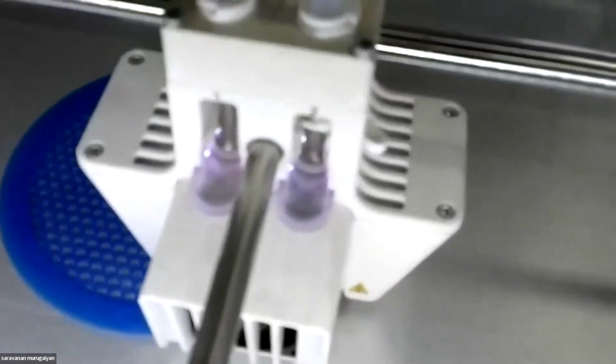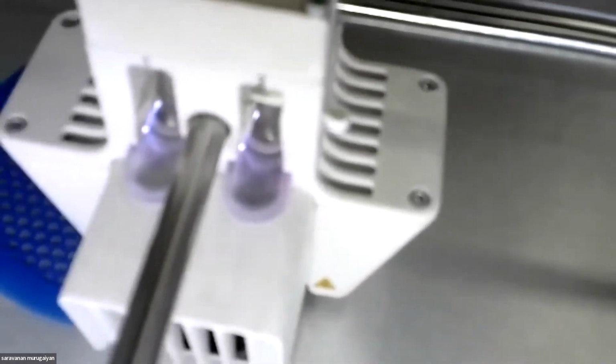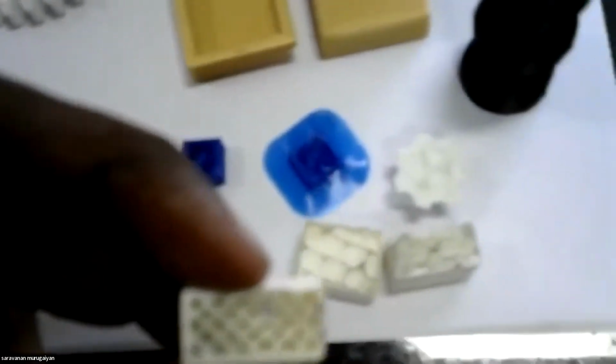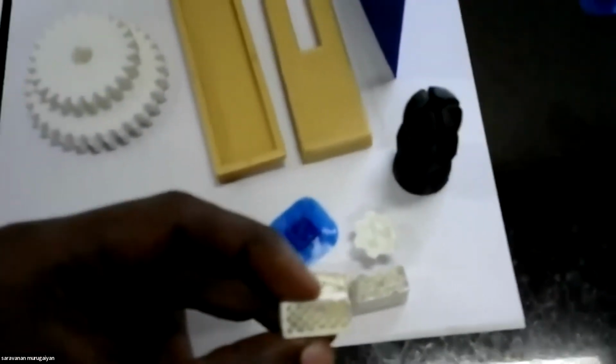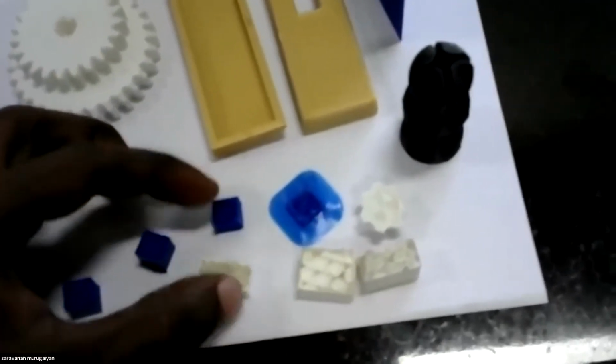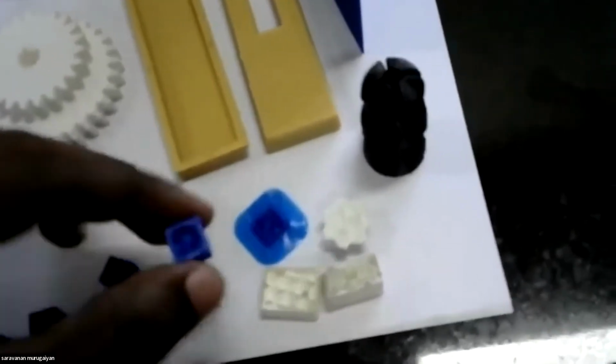As you can see, now we are printing a honeycomb structure, which is not that porous, so it is completely filled. That is, the infill density constantly remains 100. But in some cases wherein the material has some hollow structures in between, the infill is to be given with some definite patterns. This is the infill pattern of rectangles that we tried, and this shows the infill pattern of